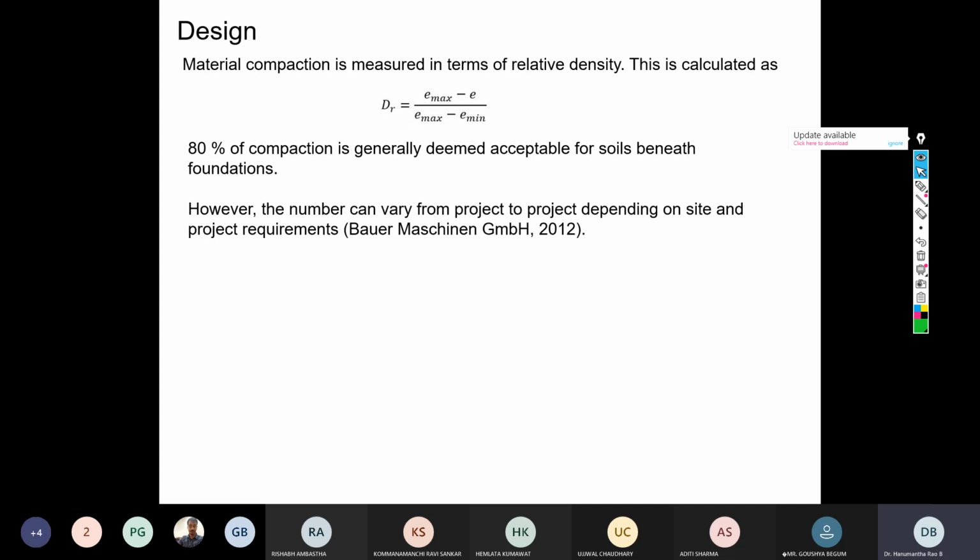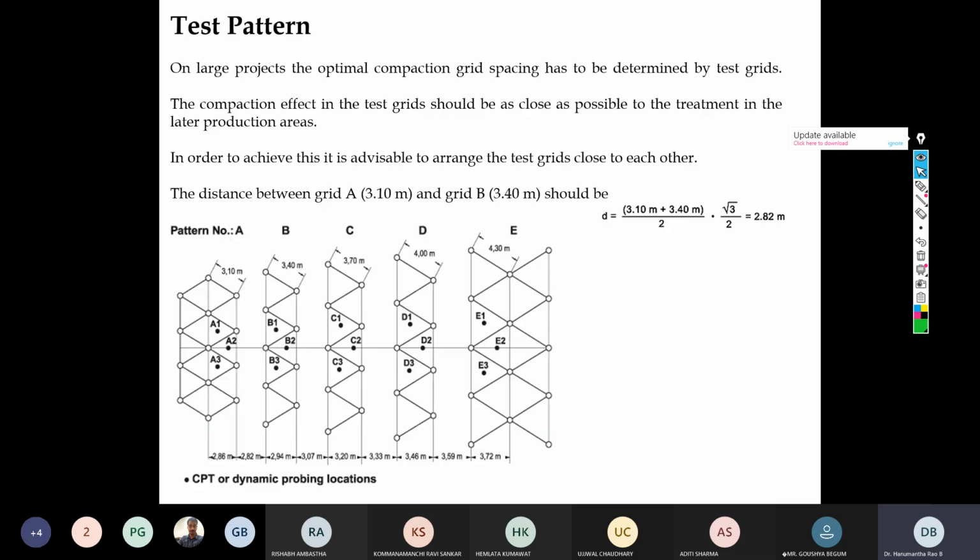The basic reason is that the vibroflotation technique is fundamentally ideal for sandy type of soils. So when you talk about sandy soils, the relative density is the measuring parameter to ascertain the degree of improvement. Therefore, we normally measure the relative density as shown in this formula. How much should be the relative density value? That we have already discussed in yesterday's class.